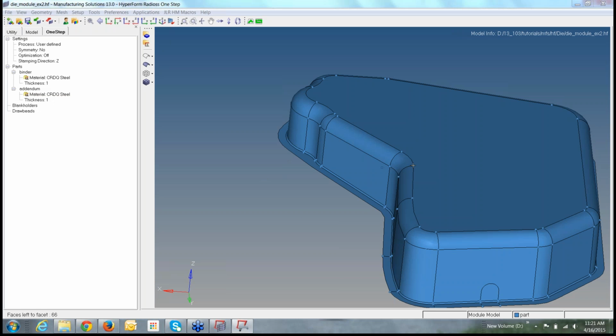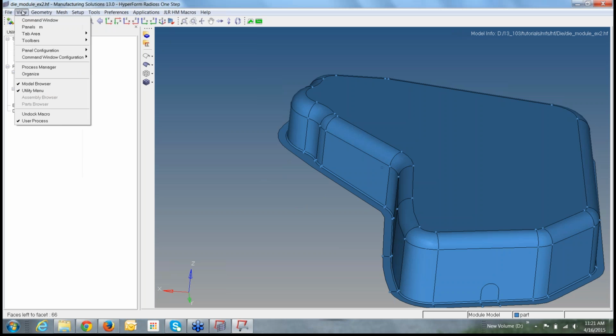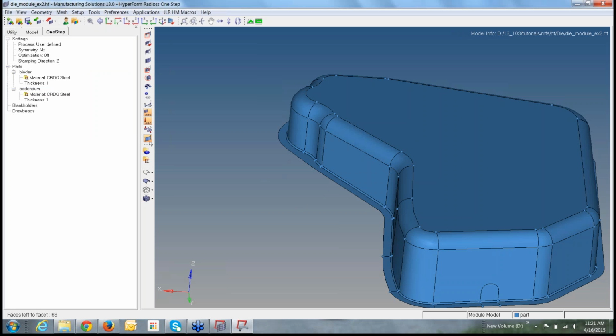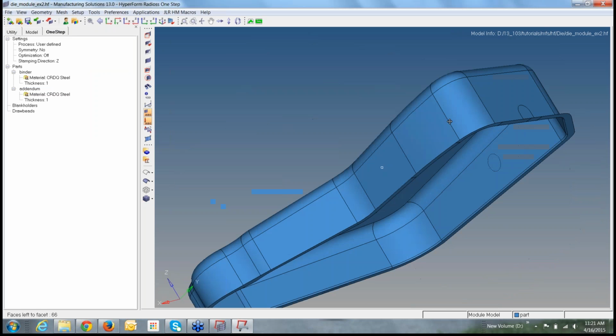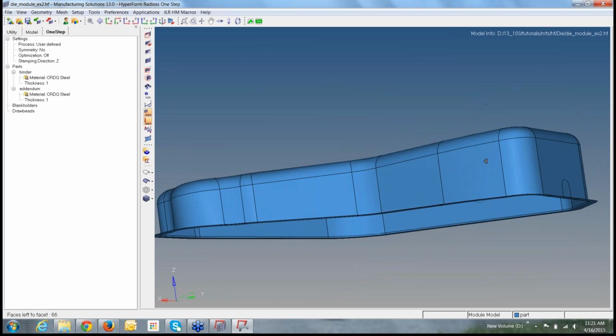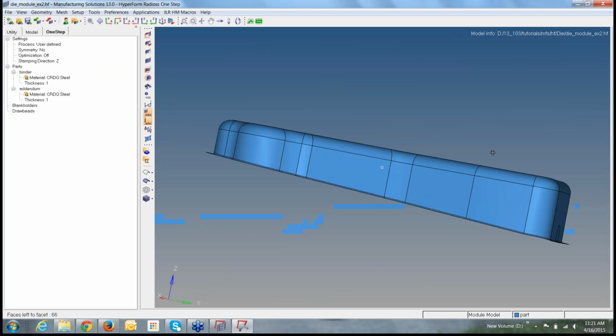You can hide these dots using View, Toolbars, Display, this button here, Display Fixed Point. So this will hide it. These fixed points will affect your mesh flow, hence they should always be hidden. So here is one component typical of your forming stages.